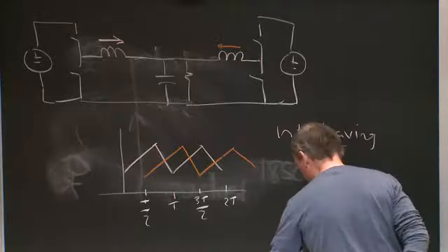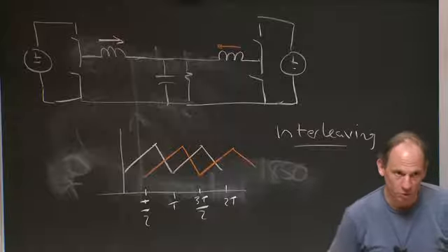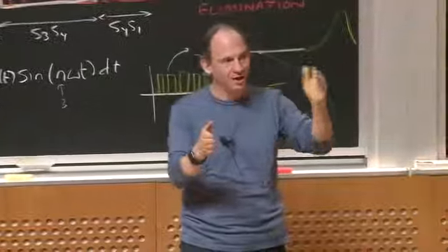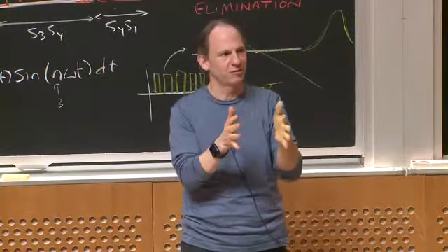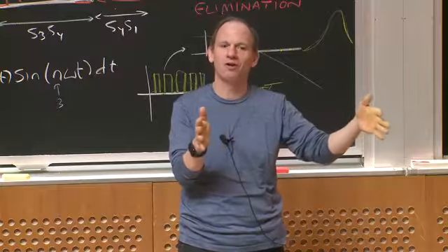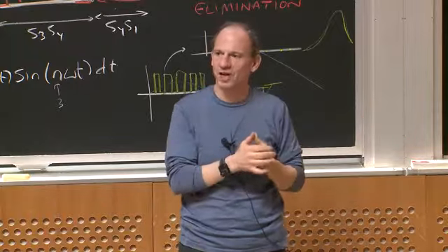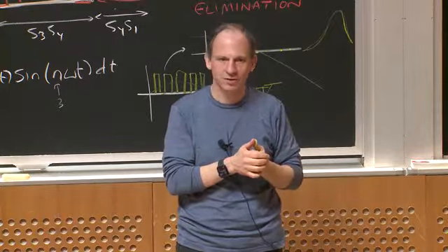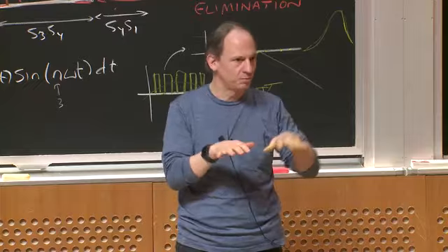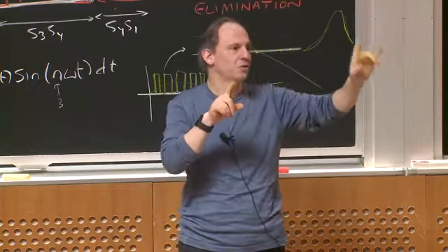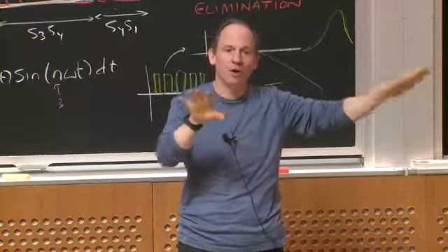It's very widely used, and in fact, most motherboards, if you look at them, don't have a single buck converter driving the load. They'll have a whole bunch of buck converters lined up, and they phase shift them all such that the first N harmonics will go away, and the ripple frequency will be much higher than the switching frequency of the individual converters. That also means you can play with response speeds, because one will react much quicker than if they were all in phase.